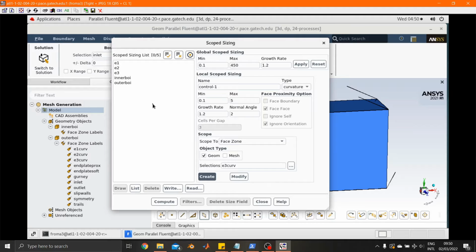And so we're going to want very, very small, fine mesh right there around that area. So instead of curvature now, because the gurney flap isn't curved, we're going to set this to hard. Now, a type hard means that on the whole surface you select, it gives it a size mesh to sort of look for, and then it forces that whole surface to be of that size.